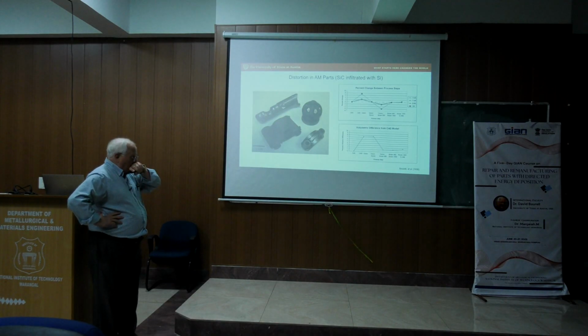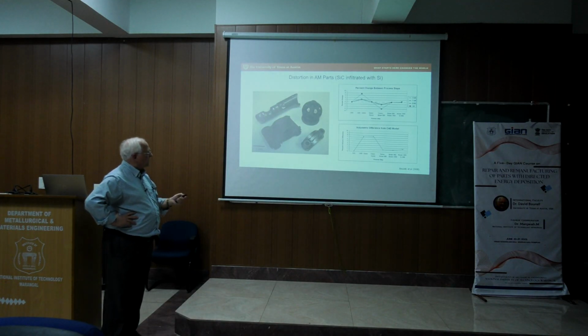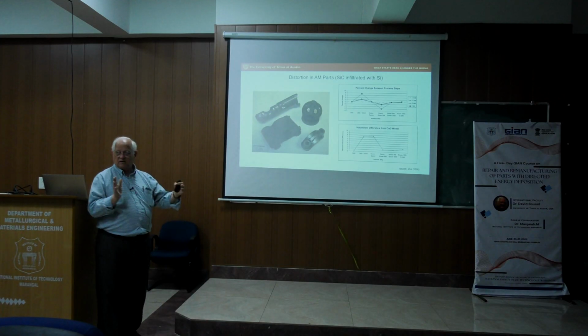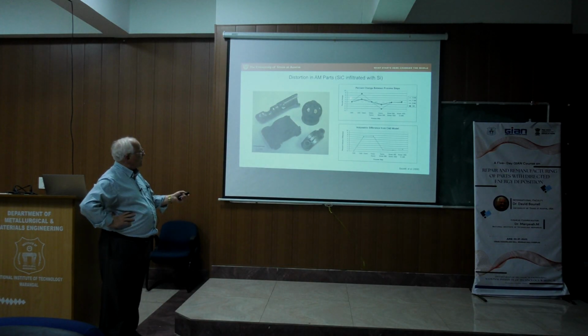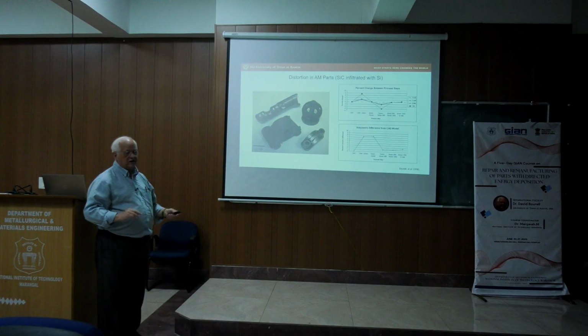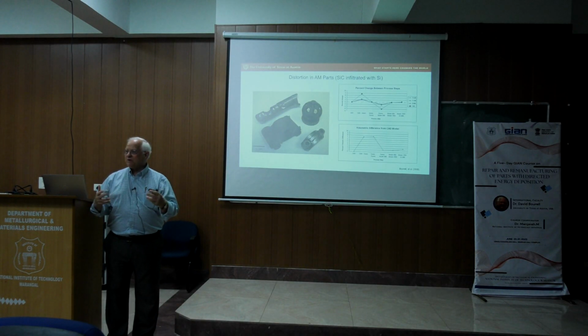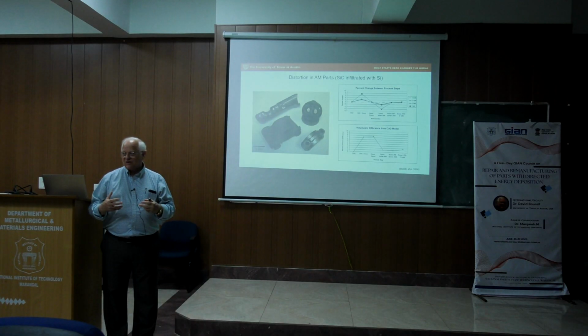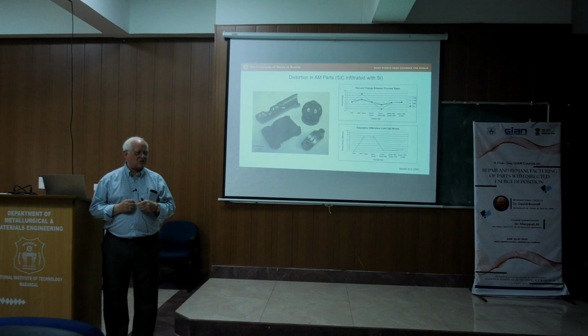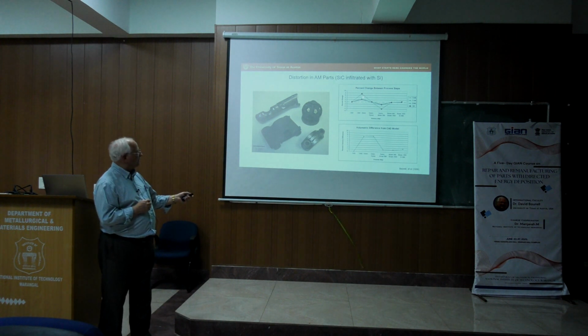And that's the linear strain distortion. It turns out that you can also calculate a volume strain. If you have the principal strains, which is the case here, the volume strain is just 3 times the linear strain. So basically, this is going to be 3 times this curve.